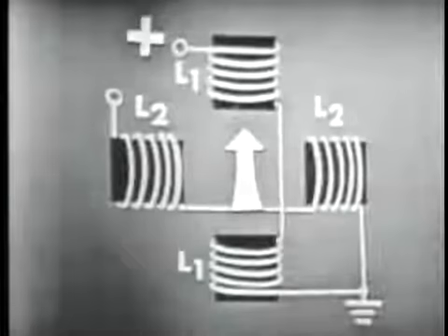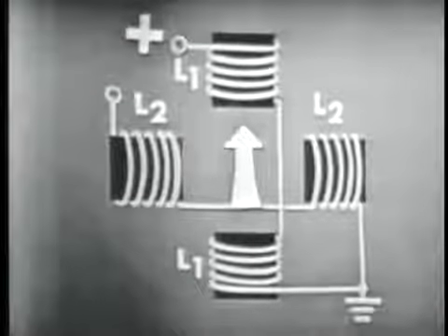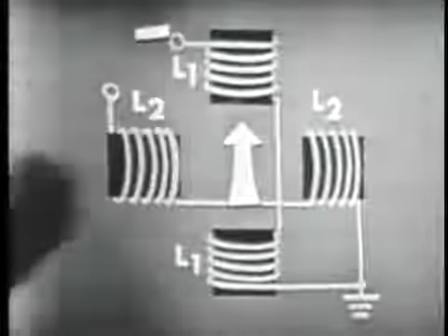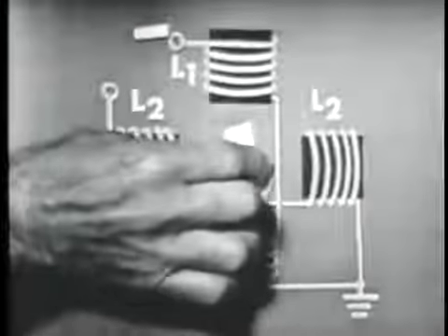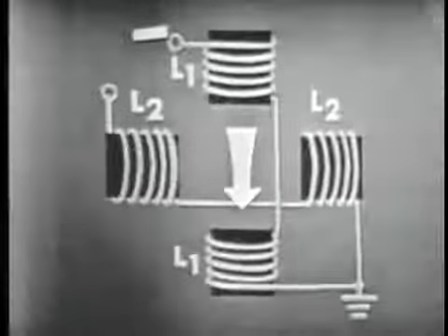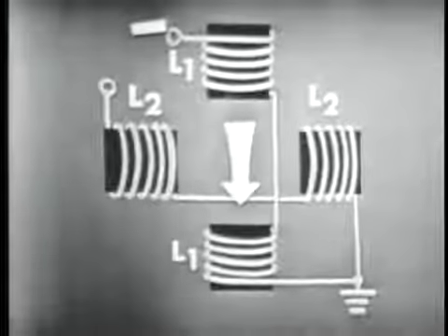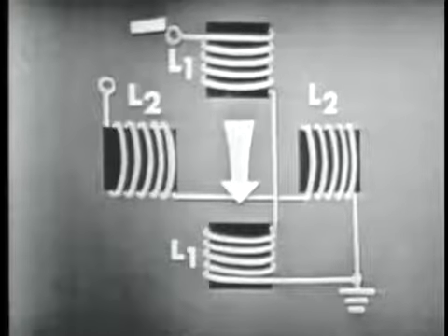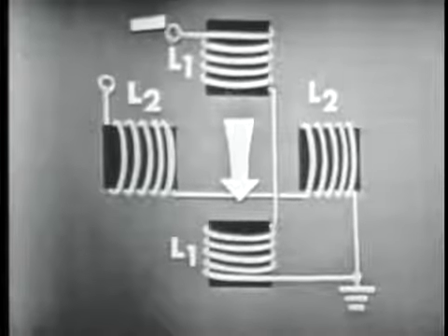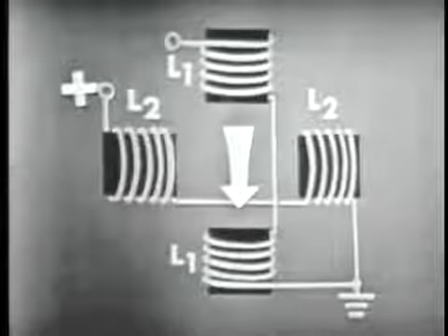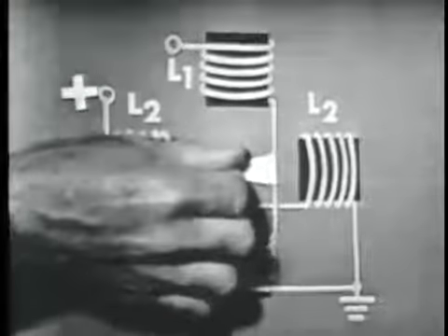Another good point is if we reverse the polarity on L1... Make this a negative, in other words. Right. We'll, of course, reverse the direction of the magnetic field produced by L1. And the rotating magnet will again line up with this magnetic field. Now, the same thing, of course, applies to L2. With voltage applied only to L2, we'll produce a horizontal magnetic field. Like that.